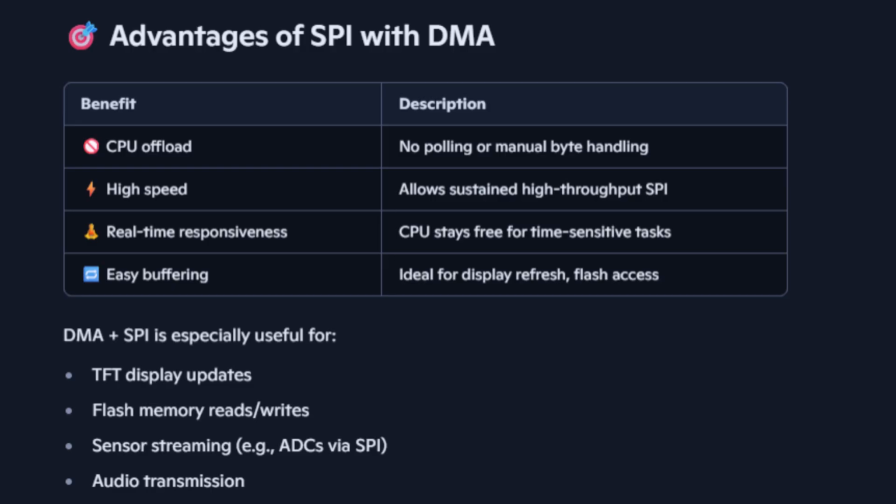5. The DMA engine then automatically handles everything. As each byte arrives in the SPI receive register, the DMA controller grabs it and puts it into your RAM buffer without the CPU doing anything. Simultaneously, the other DMA channel might be feeding dummy bytes to the SPI transmit register. 6. Once the specified number of bytes has been transferred, the DMA controller triggers a single interrupt to the CPU, signaling transfer complete. 7. Your interrupt handler then knows the data is ready in the RAM buffer, and it pulls the CS line high. So the CPU just sets it up and gets an interrupt when it's all done.